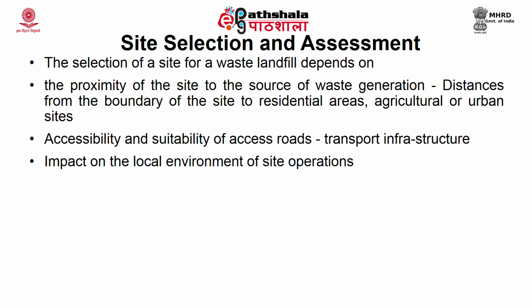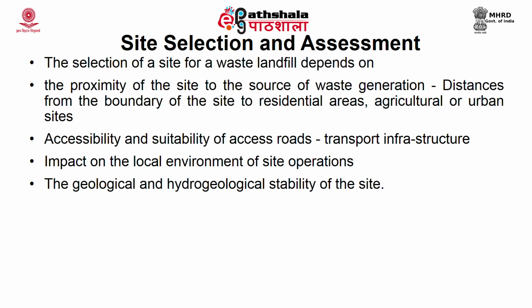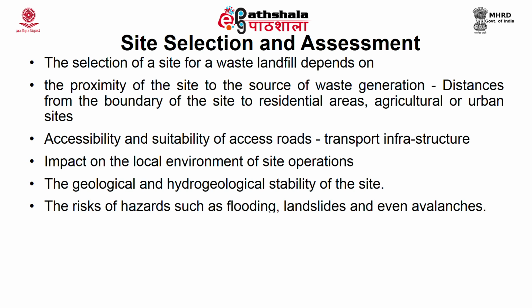Then the impact on the local environment. When you select or allocate a site for a landfill, you should study how the landfill is going to affect the local environment around it. Next, you should also consider the geological and hydrogeological stability of the site. Also, these sites should not be located in a place where there are chances of frequent flooding, or where landslides or avalanches can occur. So, such areas should be avoided.